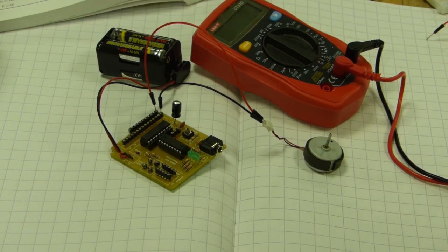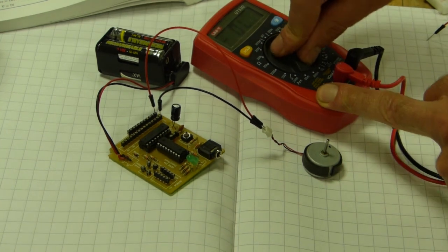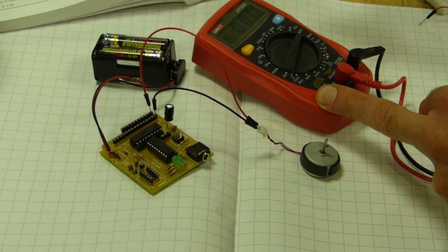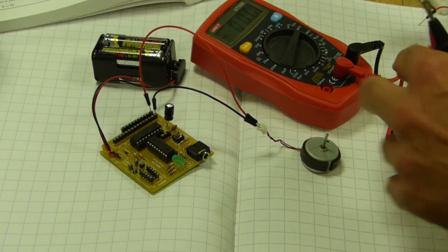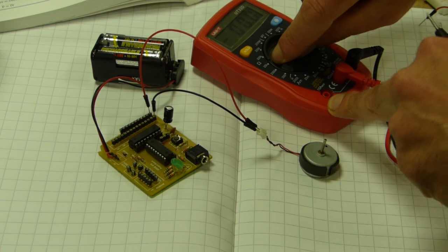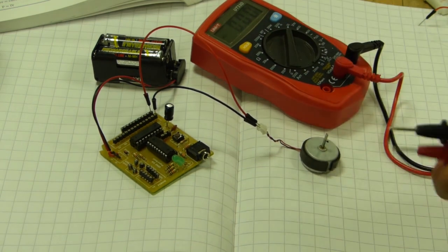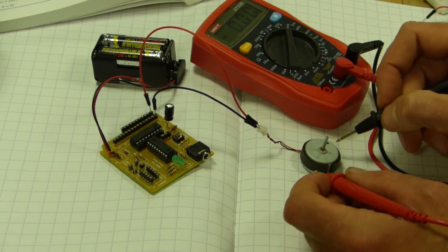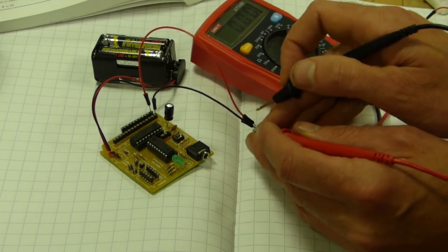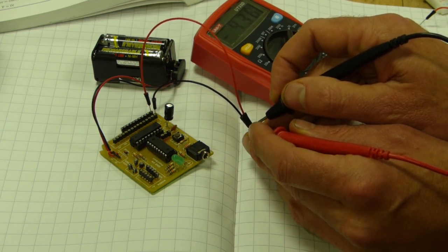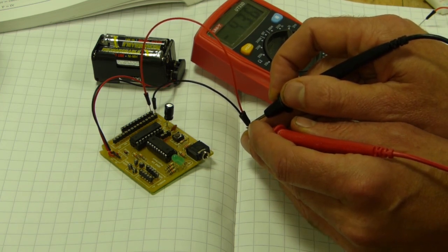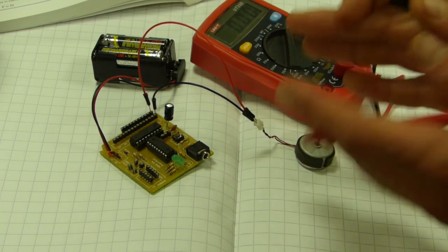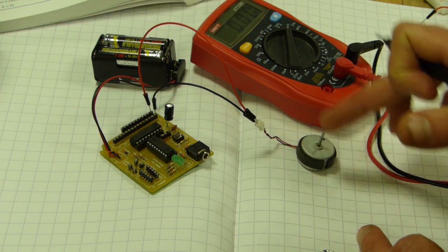So when using it to measure voltage, what we do is, like with resistance, we choose the correct range. Now I'm using 4 AA batteries here, so it's about 4 to 6 volts. So similarly, I'm going to go to the next highest amount, which is 20 volts. Now here, I'm measuring across something. So in this case, this little motor is running away. I want to be careful not to short these wires, but just touch either side of it. As you can see, I've got the red and the black the wrong way around. It's coming out negative 4.36. So I'm measuring the potential difference across this motor.